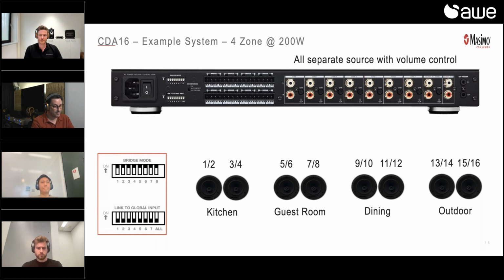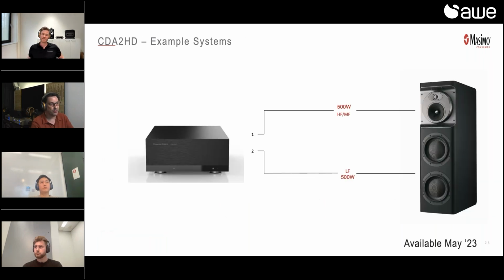Okay. Then about the CDAs, those are distribution amplifiers. Are these amplifiers to be used exclusively for CI and CT speakers, or can they be used for others? Let's say floor standers, components. Just one slide I think that you showed where you had high frequency and mid frequency for one channel and a low frequency, but that's also a CT speaker. What about component speakers? Is that possible at all? This is quite a different speaker, because here we really separate the high frequency and mid frequency and the low frequency. So you need more or less 2 amplifiers to power the speaker anyhow.